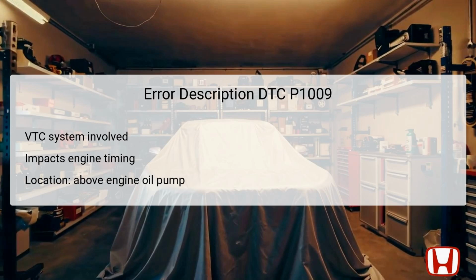The VTC strainer is located above the oil pump. It filters engine oil before it reaches the oil control valve and actuator. If this strainer becomes clogged, it can restrict oil flow, leading to timing issues. The oil control valve is responsible for regulating oil flow to the actuator based on signals from the engine control module. Additionally, the actuator itself adjusts the camshaft timing based on oil pressure. Therefore, all these components must be functioning correctly for the VTC system to operate seamlessly.